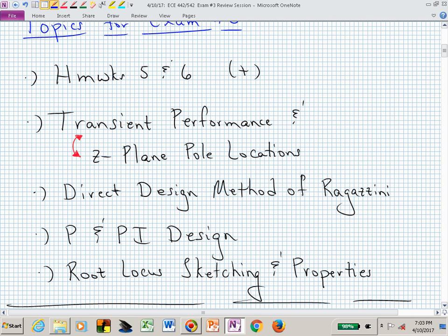So we'll get into the Ragazzini design, but the question concerned, I think, constraint number 4 of the Ragazzini design, which talks about steady state accuracy. You may want to force your desired closed loop transfer function to have a particular value or DC magnitude. You may want to force T sub C of Z to equal 1, let's say at Z equal to 1.